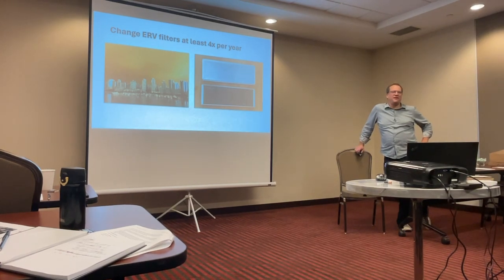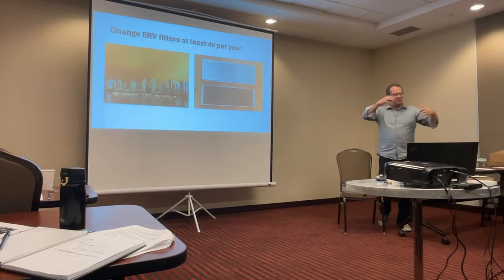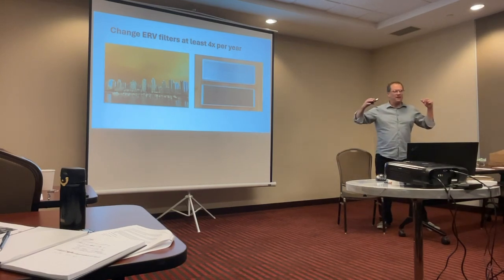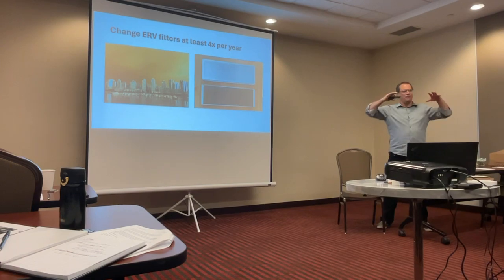This is a very emerging area of building science, as Elena touched on earlier, where we do not have consensus about the data on air quality. You could monitor a building for CO2, you could monitor for humidity, you could monitor for PM, and you would have totally different run rates and different strategies, different filtrations. And each one would be right. It's part of the confusion that's coming out of ASHRAE. Different approaches are getting very different numbers. And we do not have, that I'm aware of, a building science and health consensus on where we should be.